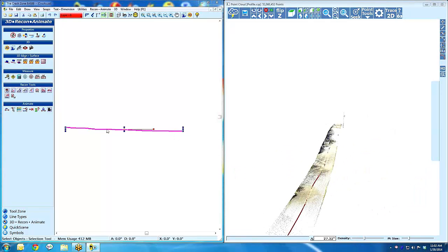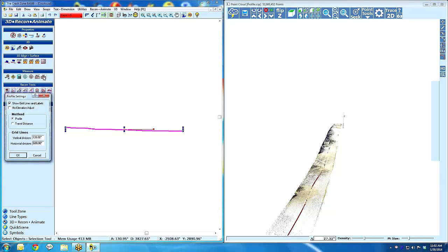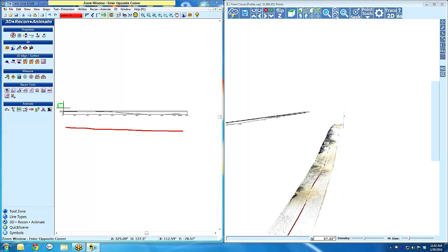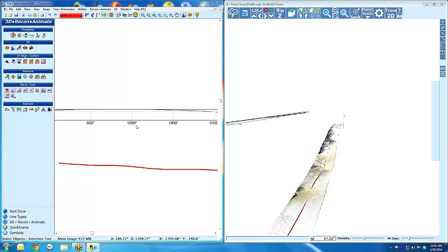And if I just select it and go into the profile tool right here, let me go to settings first and do a profile 120 degrees, 600, just showing the divisions. And all I got to do is click on the profile tool and done. There it is right there. I'm in inches. I'll delete this.